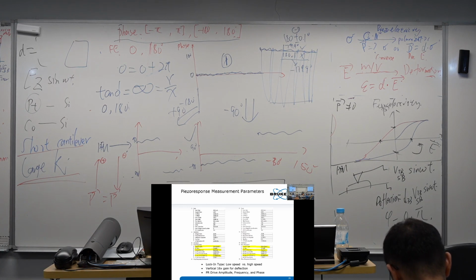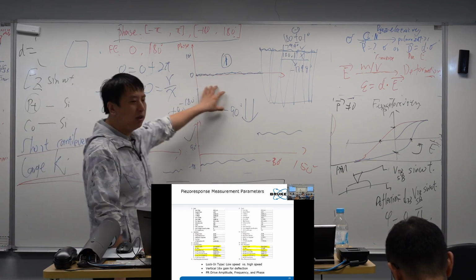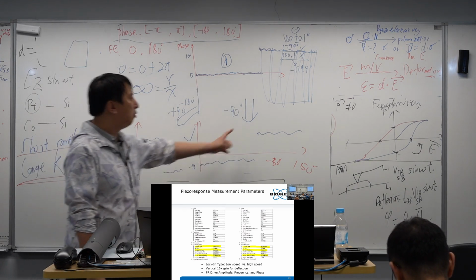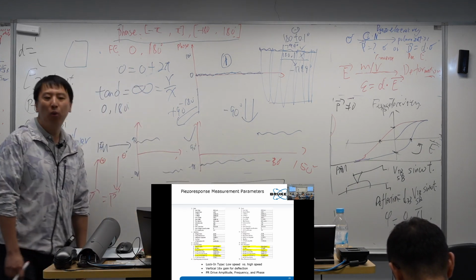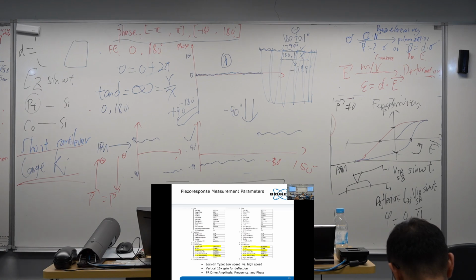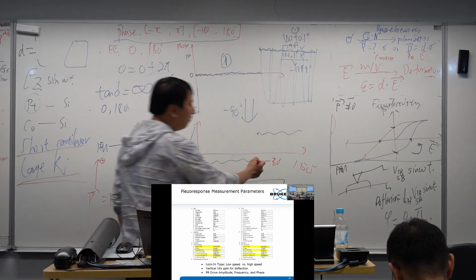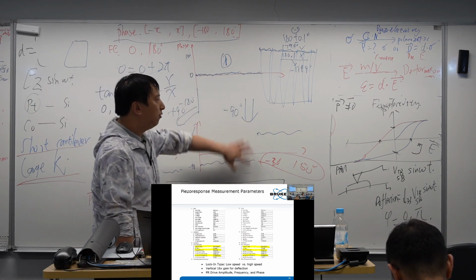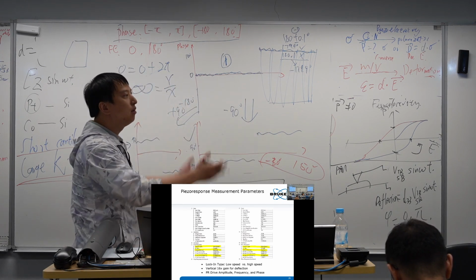But it's just today's community. Some reviewers, they don't remember the theory of PFM. They just demand, oh, your phase has to be positive and negative 90. No. Any phase is okay as long as the difference is 180, then it's correct.